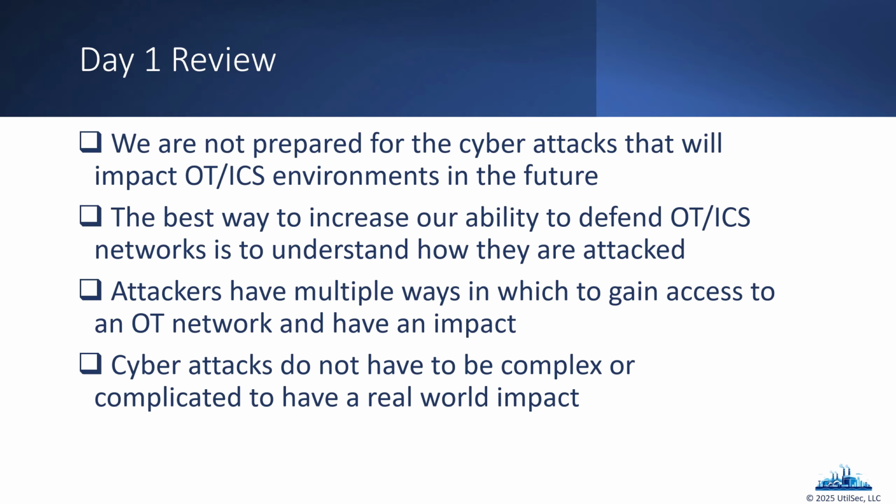But one of the best ways that we can learn to become prepared is to learn how attackers break in to OT environments. And then, of course, once they're inside, then what do they do? We're walking through that process of, okay, we got the foothold on the network. Then how do we find the different control systems? How do you find the equipment and the process in the real world that they monitor and control? And how do they do that? So we can reverse engineer the process as a pen tester or as an attacker to then understand what changes we can make to have the most impact in the environment.